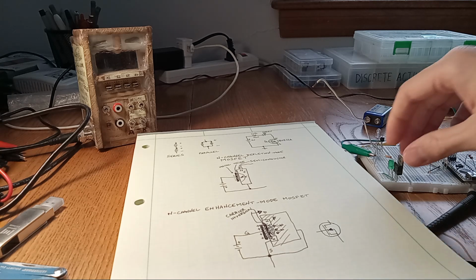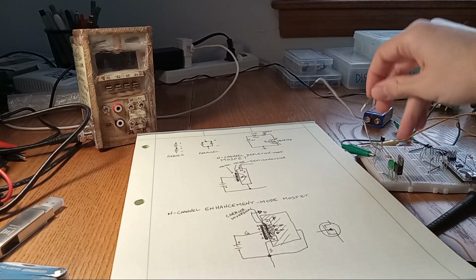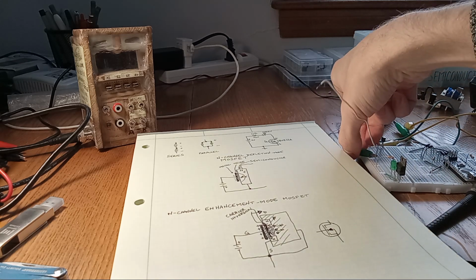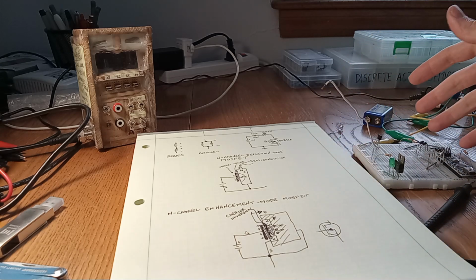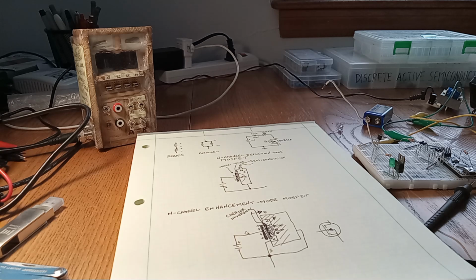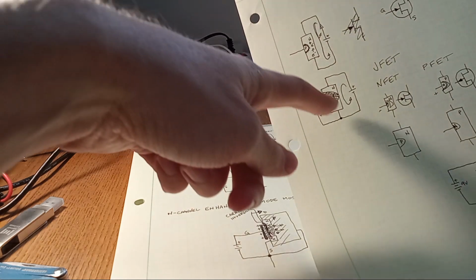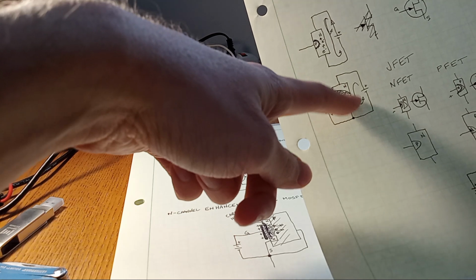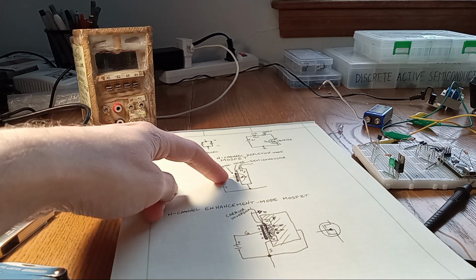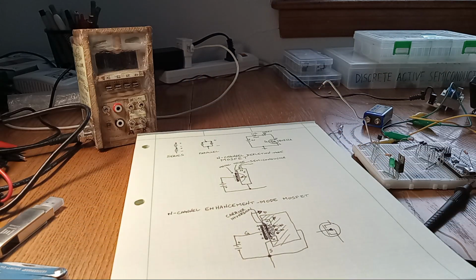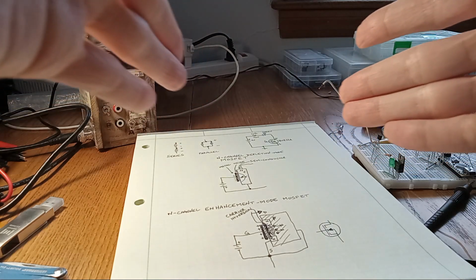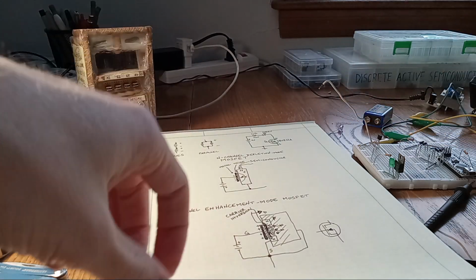So, the 2 types of transistor we discussed previously, the JFET and the MOSFET, they are both voltage-operated devices, by which I mean you control the voltage at a gate and it controls the thickness of a depletion region in the case of the JFET or the depletion mode MOSFET, or it effectively creates a new channel of either N or P-type semiconductor from the opposite type, depending on the applied voltage. Either way, you're controlling the thickness of a conductive channel with an applied voltage.